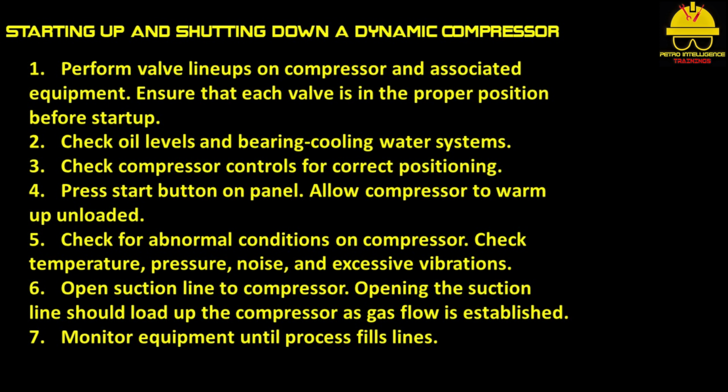4. Press start button on panel. Allow compressor to warm up unloaded. 5. Check for abnormal conditions on compressor. Check temperature, pressure, noise, and excessive vibrations.